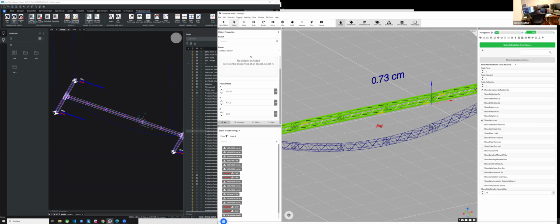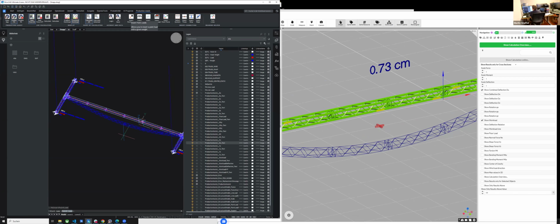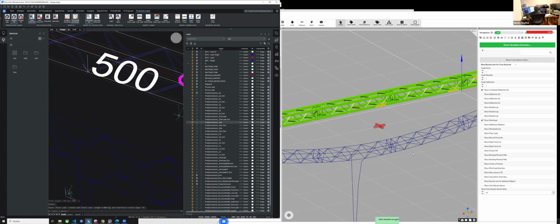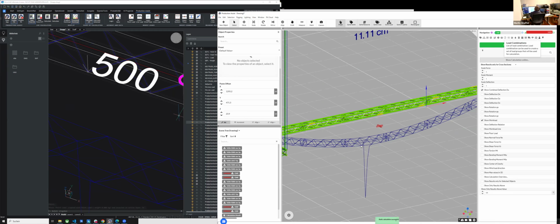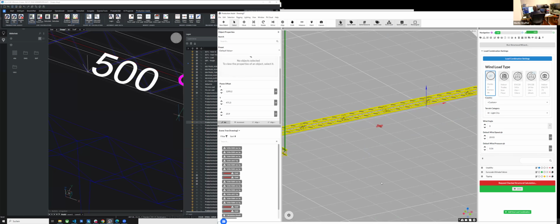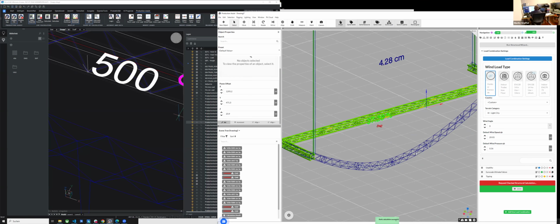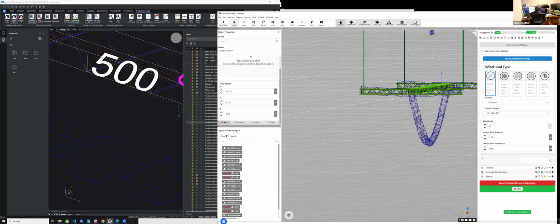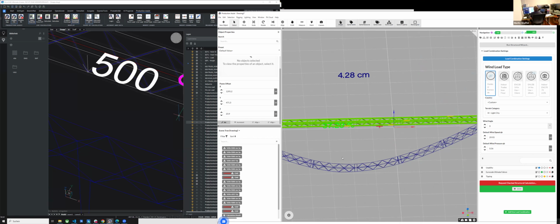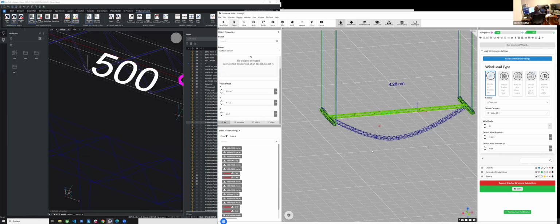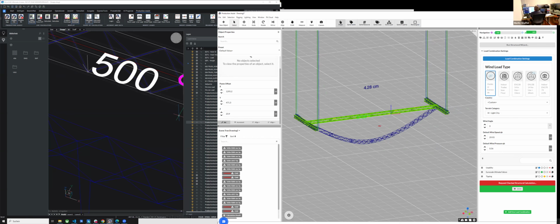And for example, an interesting thing that we can show is, if I'm adding a point load to this side, like 500 kilos, okay, place it here, you will see, wait, let me quickly, now it's failing. As you see here, a second order fail. So let me go back to the first order. You will see that now the calculation is bending a little bit to the side and that it's increasing the workload. So all of these kinds of effects can be used to calculate these kinds of things.